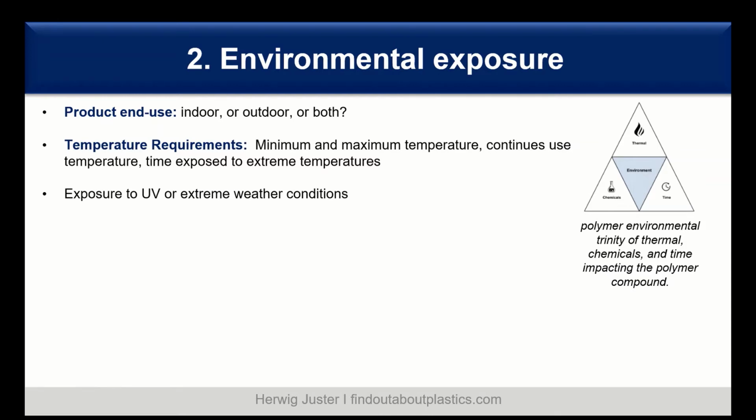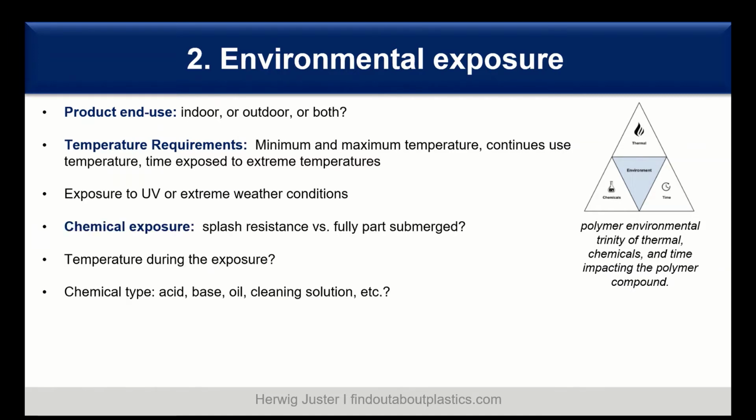And when we look at the temperature requirements, we always have to check what are the minimum and maximum temperature conditions, what is the continuous use temperature, and how much the part is exposed to extreme temperatures. Then also exposure to UV light or extreme weather conditions is important to check. And then also the chemical exposure.